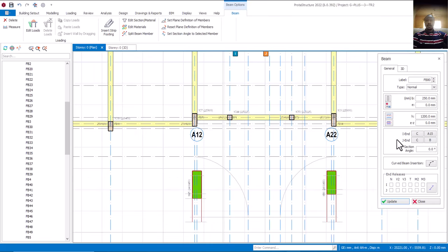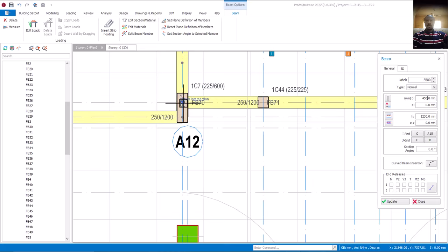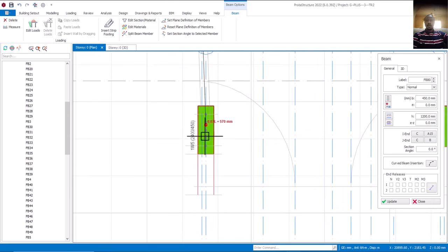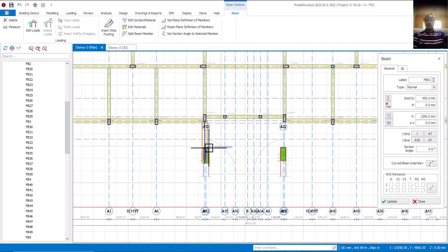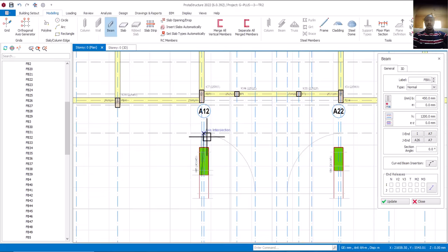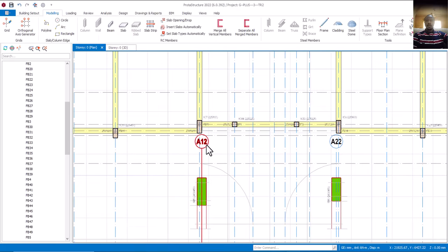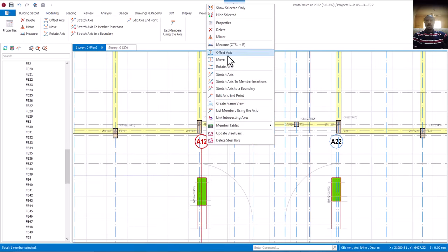So here now, I'll turn it to 450. Is that okay? 450 from here now. Let me see if it will work. Okay, to this point here. Is it here? Okay, it's outside. So I'll now press delete. Then escape. Let me click on this, right click and click on what? Stretch.